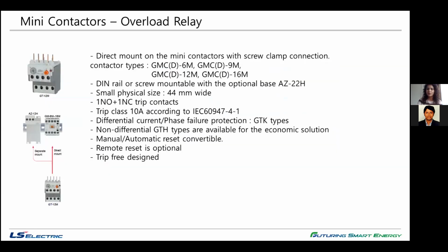Next is the thermal overload relay. It's similar to the one with contactors. You can directly mount it, or if you want, we also have a DIN rail or a screw mount option. Also, it has 2 types of relay versions, differential and non-differential. Differential being having the phase failure protection and so on. We also have a remote reset option.